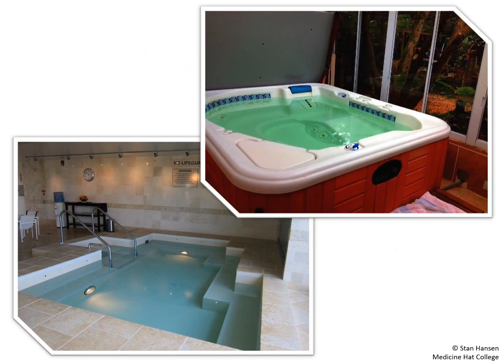When we're looking at hot tubs, we have to break them into two categories. We have the hot tub that you have at your house, and then we have the hot tub that is available in a commercial location. Either way, they both must be bonded and GFCI protected, and the controls must either be integral, so built into the unit itself, or they have to be at least 1 meter away from the tub. Any receptacles or luminaires will fall under other rules found within this section.